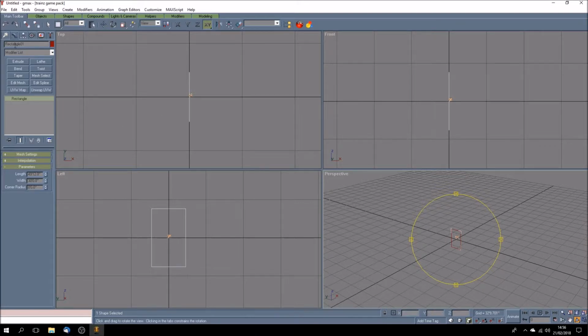So if we come back over here where we're editing it and just remind ourselves the size of it, the width is 30, but the height or length is 50 feet. So really what we want to do is, sorry, not move the center, move the whole rectangle just up, so the bottom line of the rectangle is on the 0 of the z.